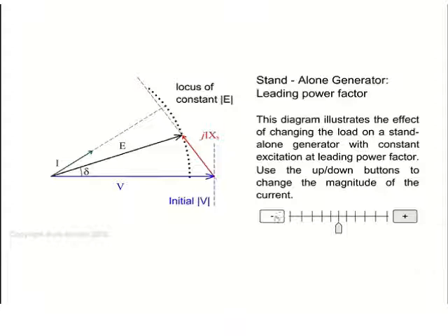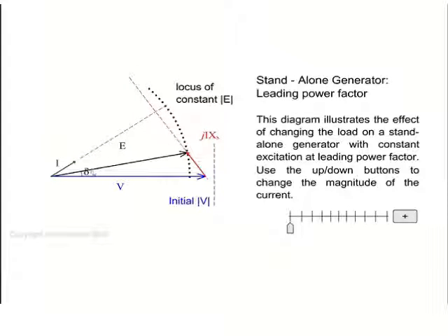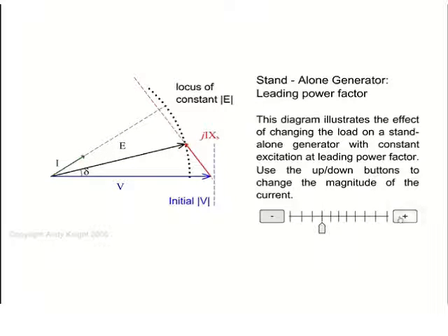Same animations we will be seeing here. You can see here the current is leading the voltage. So this is a case of a leading power factor. Now slowly I am increasing the load. So leading load is increased. As a result of it, you can see the voltage, shown by the blue color, is increasing.